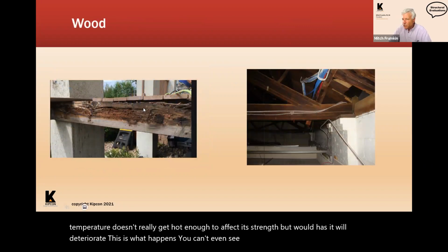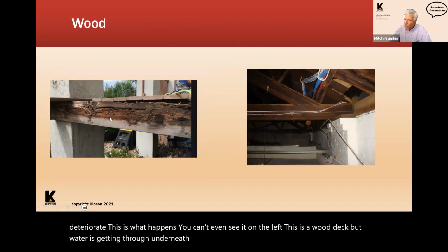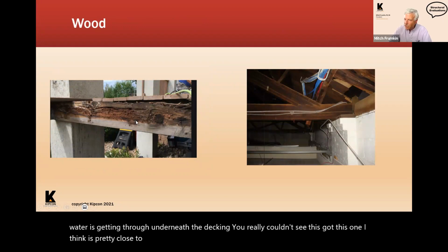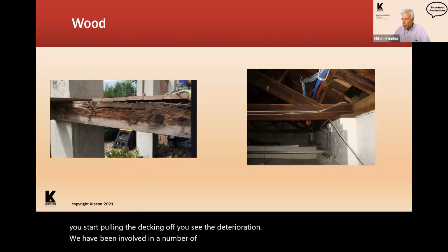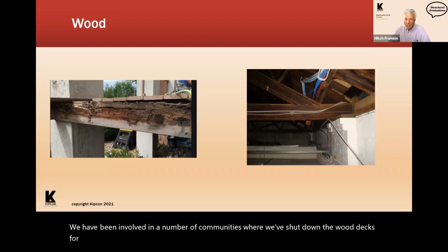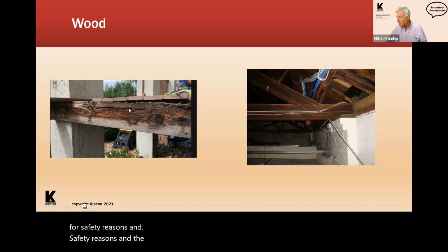On the left, this is a wood deck. The water's getting through underneath the decking. You really couldn't see this. This one, I think, is pretty close to the ground, so nobody's climbing underneath to look at it. But when you start pulling the decking off, you see the deterioration. We have been involved in a number of communities where we've shut down the wood decks for safety reasons, and they're replacing the decks because of these types of things.